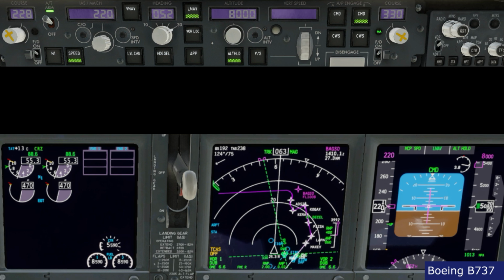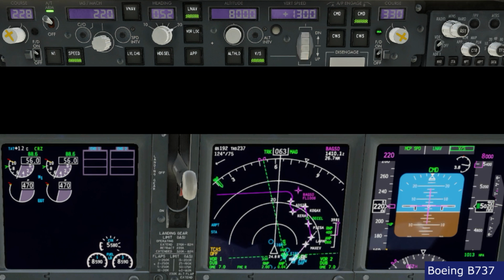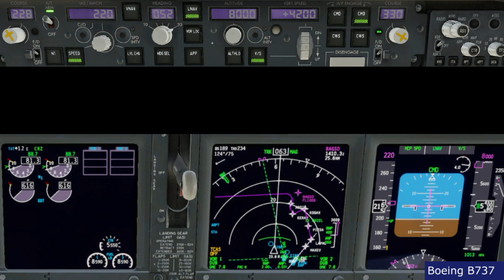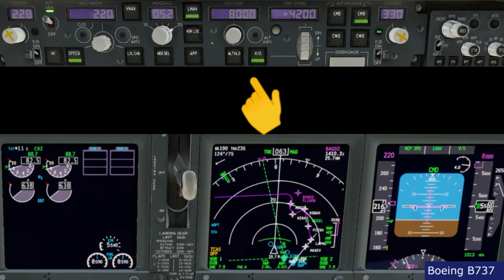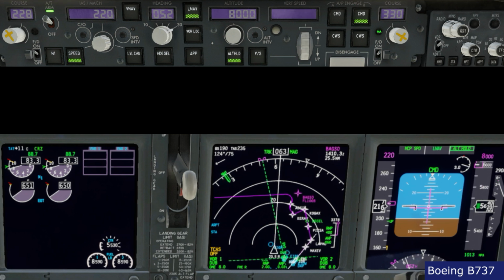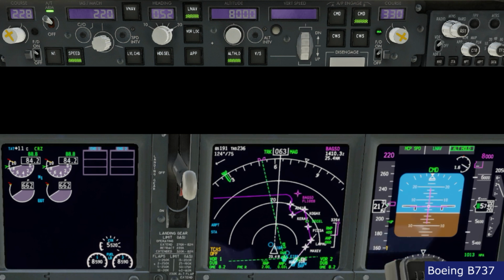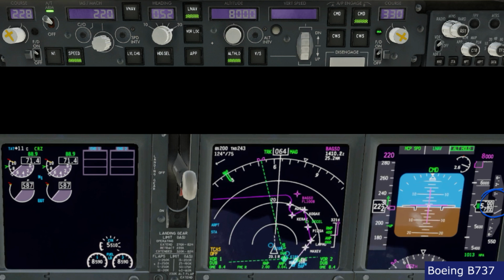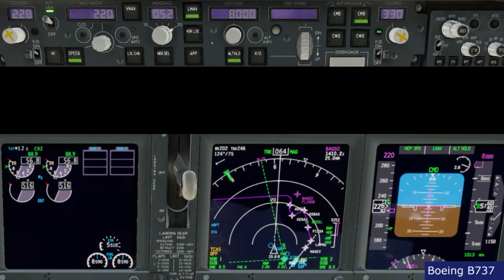So altitude hold is a function that indeed maintains the altitude. Now, I select vertical speed. And we start climbing. That's at a fairly high rate, okay? And what happens if I command altitude hold? As I said, we take a picture. So at 5,500, now I selected altitude hold. So the system took a picture of 5,500 feet. And now the function of altitude hold is to maintain 5,500 feet. So you see that we are descending back to 5,500 feet.